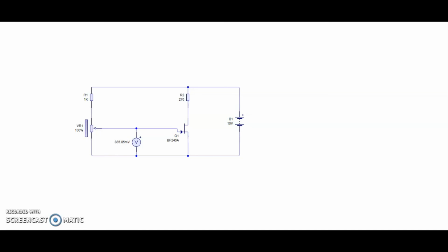So when the gate is negative, the free electrons will be pushed out of the channel, which causes the free carriers to become few. The higher resistance in the channel will make the source and drain current decrease.